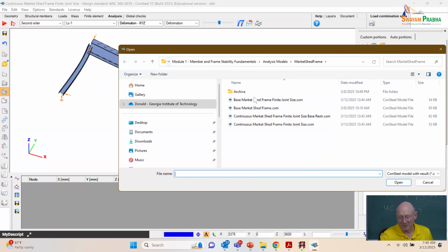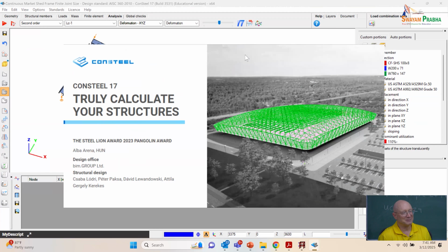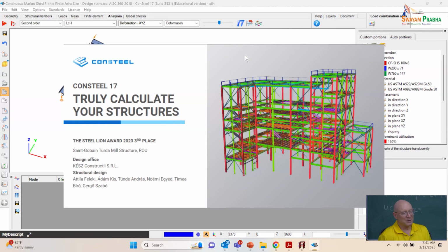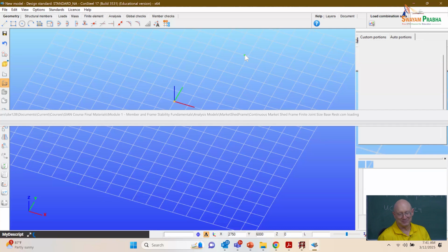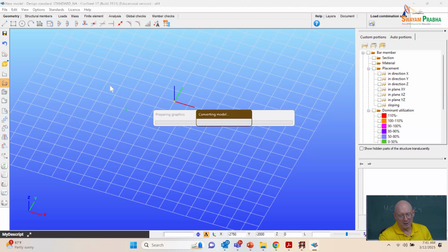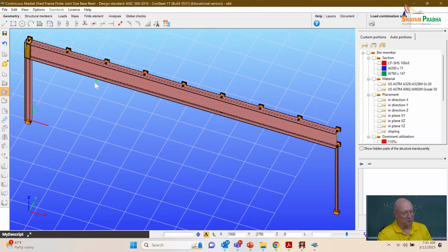So let's go to a third model where we're going to put in a rotational spring to represent some incidental restraint that we would get from a simple column-base detail. So as I understand it, in the Indian code, it doesn't tell you how to model column stiffness, but it makes a comment about you should use 10% of the column stiffness.